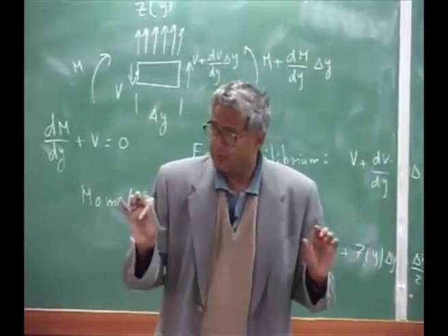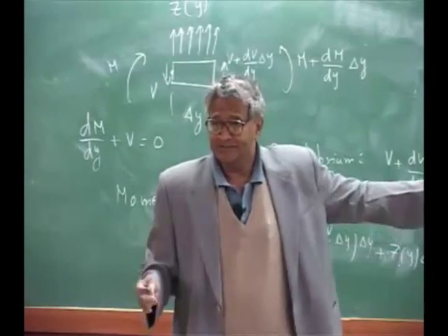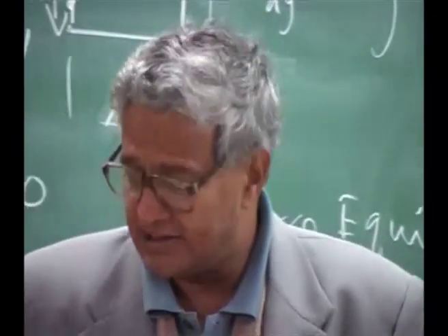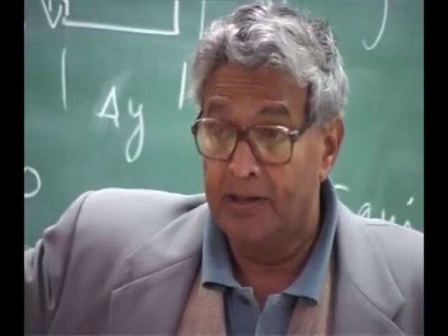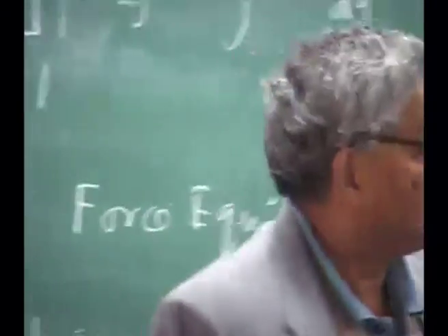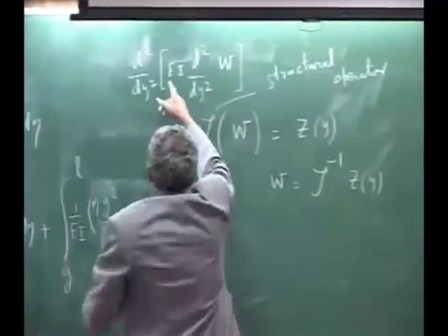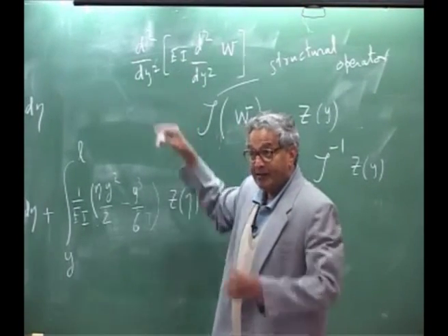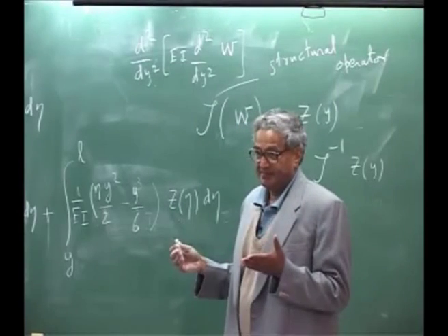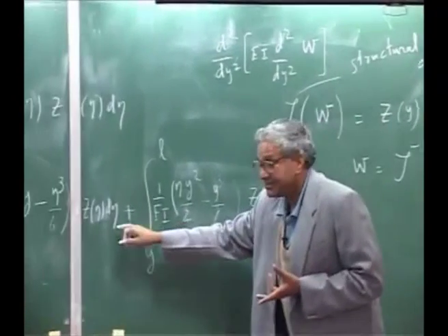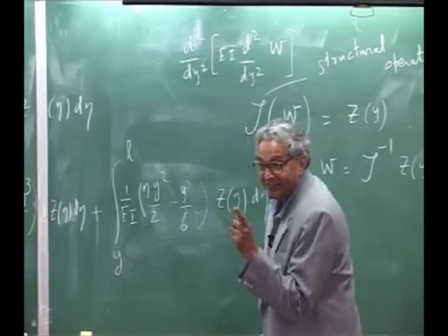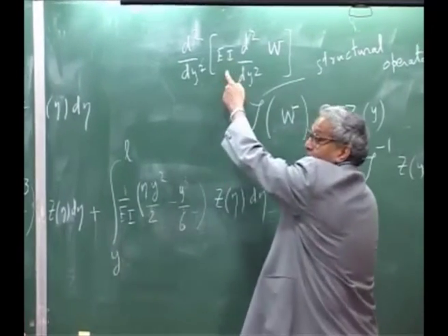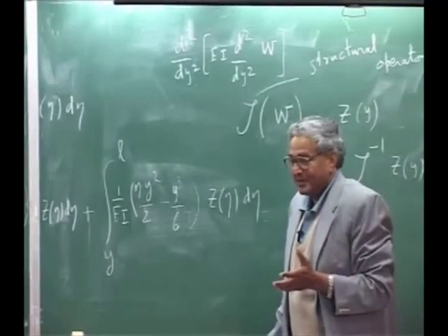Because EI is uniform, you are getting all this, Euler-Bernoulli. Suppose EI, that is the bending stiffness, is not constant, because the aircraft wing is not constant, it is varying. Now how do you do it? That is why, please remember, I put EI inside. If it is a constant, I can take it out, then I can write the solution. I can allow EI to be a function of y itself. Then this solution is not valid, because this solution is obtained with uniform EI property. Please understand, if I have a variable EI completely, I can't write this.